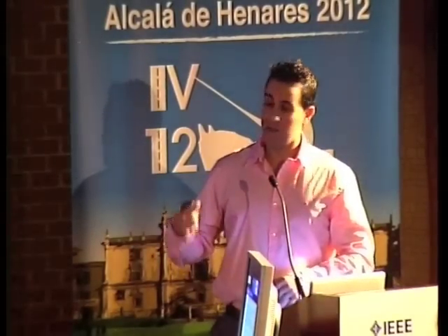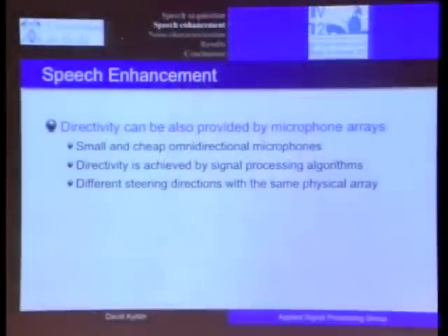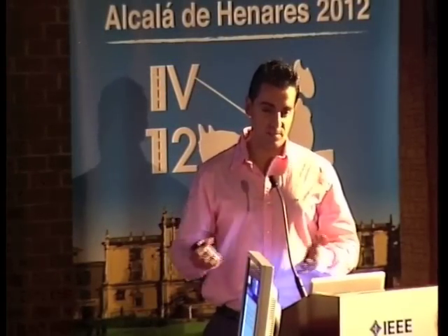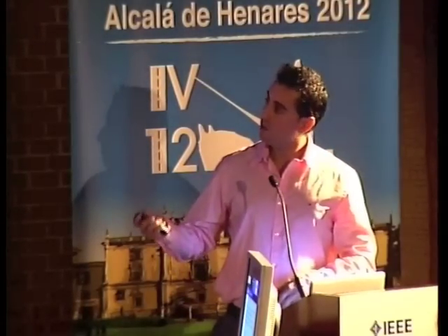However, directivity can also be achieved with omnidirectional microphones by means of signal processing algorithms with spatial filtering. They have several advantages. Omnidirectional microphones are very small and much cheaper than directional microphones, and we can change the steering direction just by calculating new filter coefficients for our processing algorithm instead of changing the physical microphone.